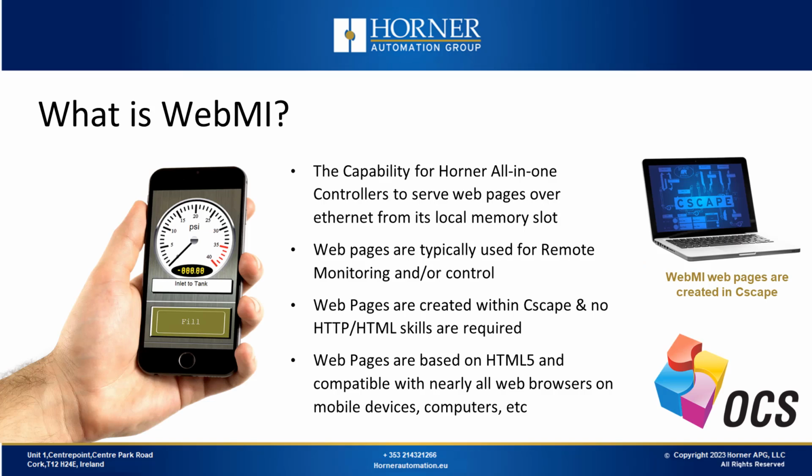WebMI is the capability for Horner all-in-one controllers to serve up web pages over Ethernet from their local slot. These web pages are typically used for remote monitoring and control. Web pages created through WebMI are done so through Seascape, and you don't need any additional programming knowledge. The web pages are created using HTML5, meaning they're compatible with nearly all web browsers.